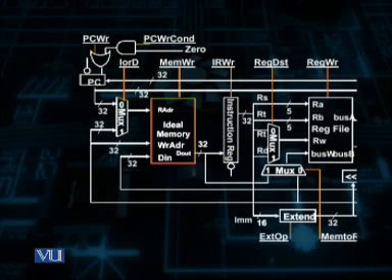Sometimes they may be used, sometimes they will be ignored. For example, in case of R-type instructions, these values are the operand values, and they are made available at input B or in the B register, which we have said is an additional register added over here.